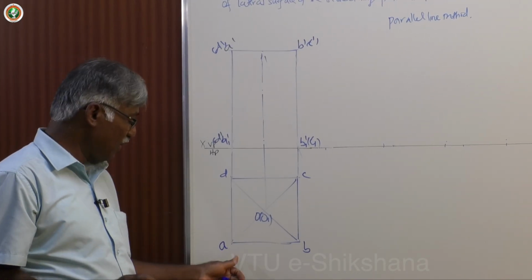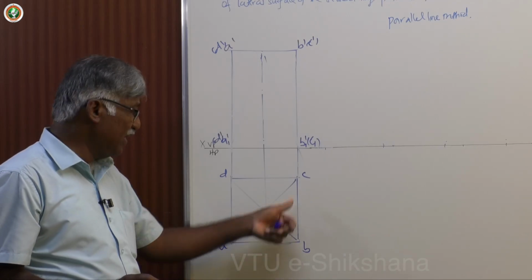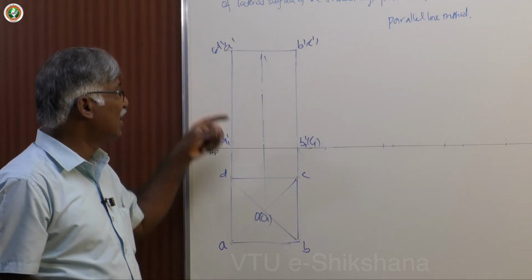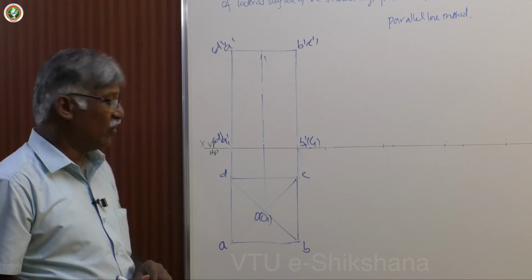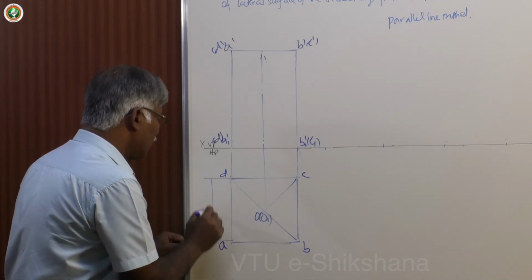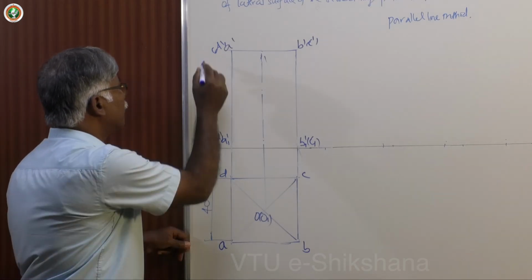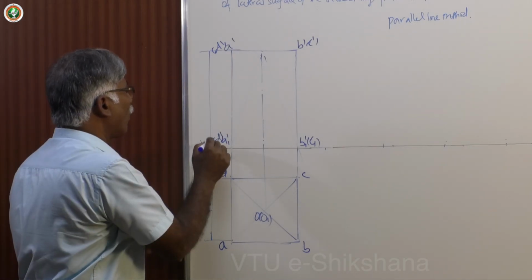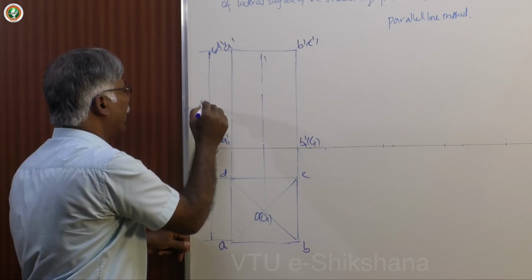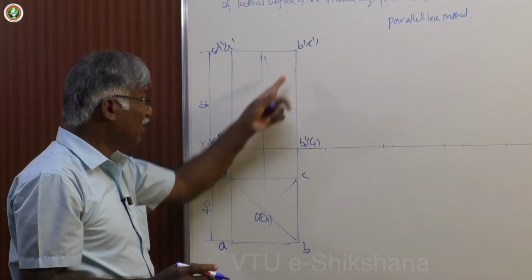So you must have the extreme right edge as the starting point, A, B, C, D, then project it and get the respective front view. Now dimensioning, as usual: the value is 40, height is 60. Naming: AA1, BB1, CC1, DD1, fine. These are all the vertical edges.